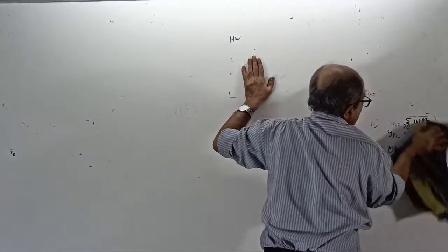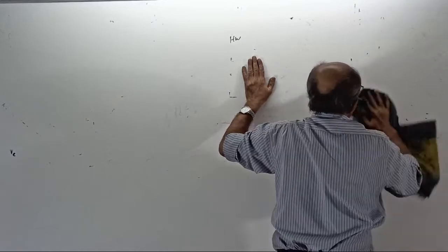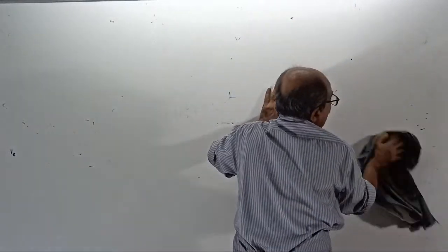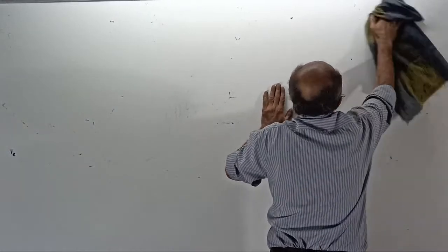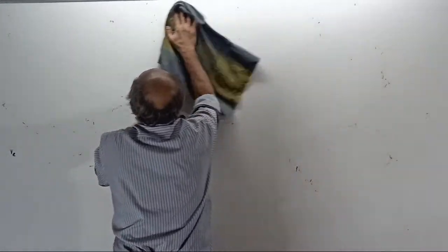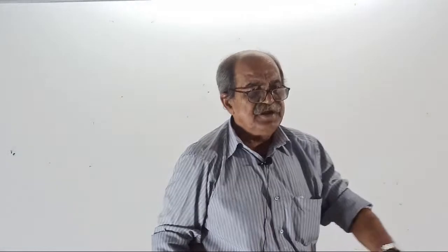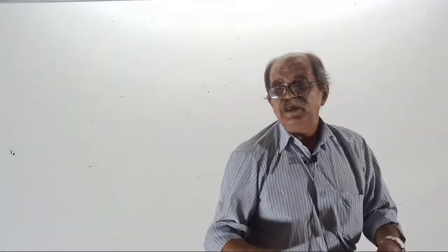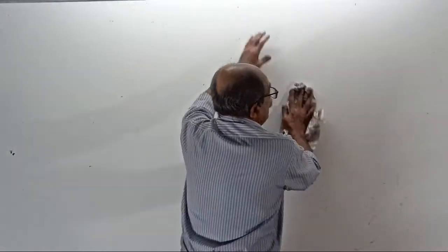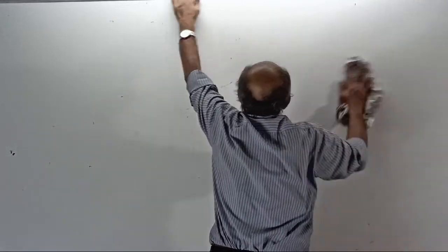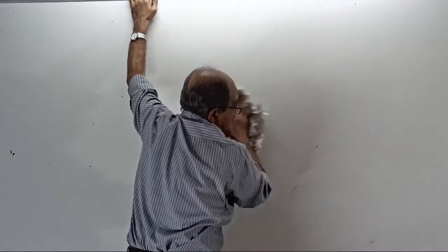Now, the next question is a very powerful question. Remember, when you design steel beams or RCC beams, usually you go for deflection control based on L by D ratio. Correct? Usually people don't calculate deflection for RCC beams. But in steel beams, many times you get 2-point load symmetrical at either 1/3 span or 1/4 span. Have you seen that one? In steel beams, 2-point load comes. In a gantry girder, because of the crane, you get 2-point load. Then you have to go for deflection check.